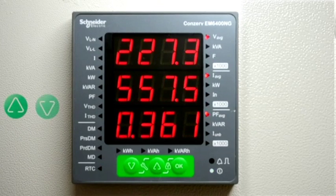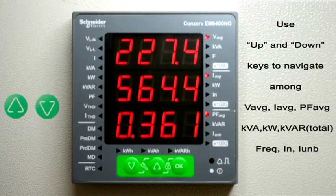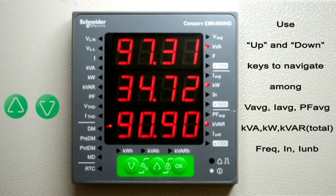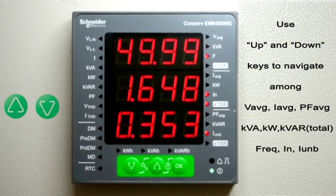There are 3 subsections. First section is voltage average, current average and PF average based on the wiring type selected. Second subgroup is total power, VA and VAR, and the last group is frequency, neutral current and unbalanced current.